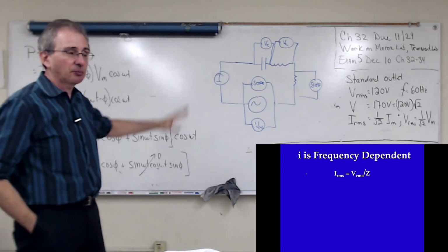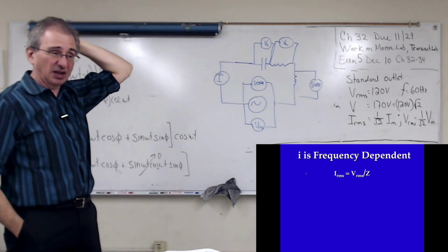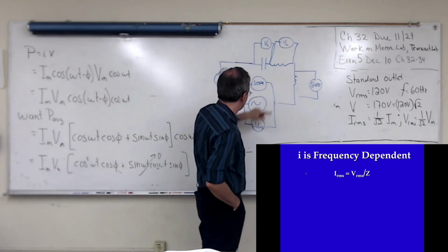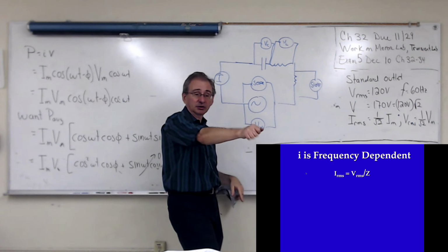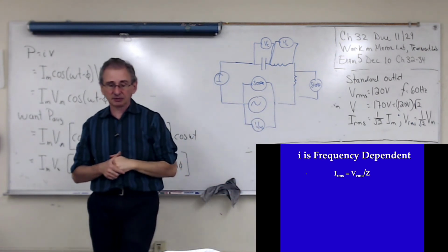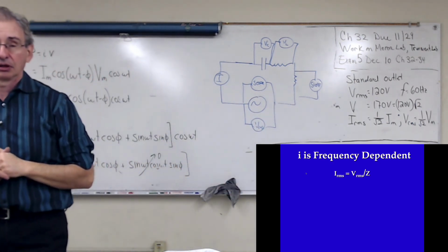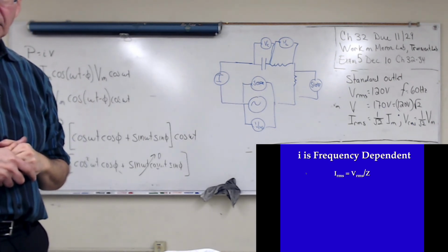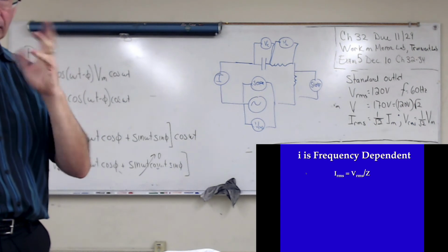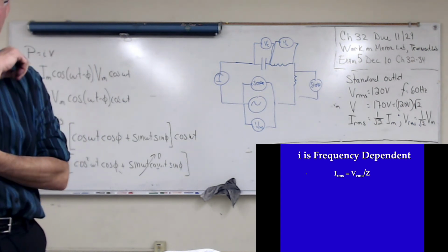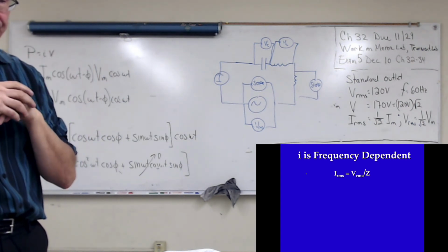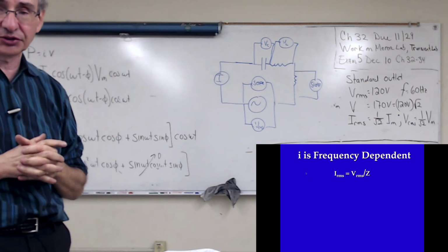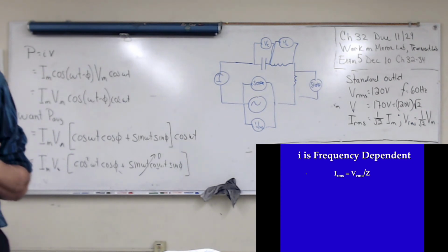Okay, but the scope, you're going to just be observing. You're going to be measuring this, this, and you'll be monitoring the RMS voltage as you're changing the frequency, because sometimes it changes. Okay, that's your circuit. It's essentially the same. So what you want to do is wire the RLC circuit like you did for the transient lab, and then hook the instruments up into the circuit. Always, because otherwise it's going to look too complicated.